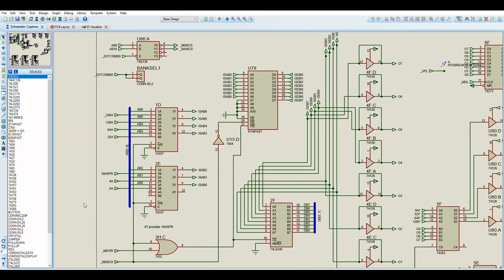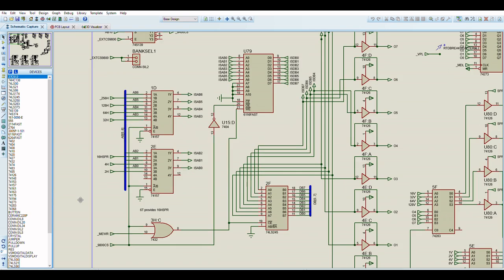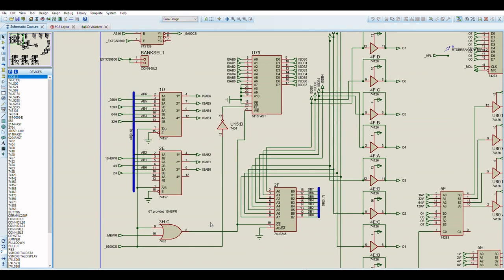because I won't be tying directly into the CPU's memory space. I'll be using an easier to interface memory access system, probably via something like the user port, and I wanted to make it one direction for only writing, really. So I stripped out all the read logic, made it a lot simpler.